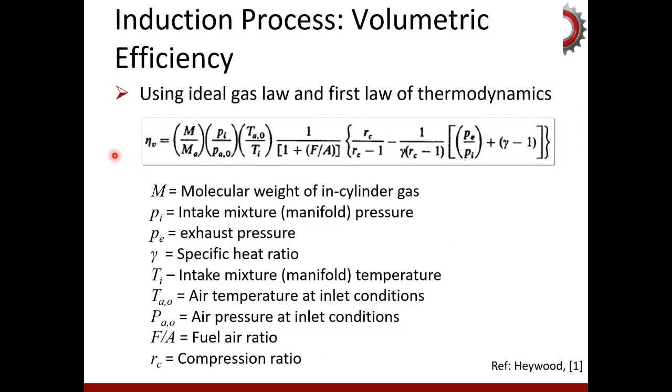So in terms of intake pressure, atmospheric pressure, compression ratio, exhaust pressure, and so forth, all these parameters have a certain effect on the volumetric efficiency. And when it comes to designing the intake system, it is very much important for us to make sure that the volumetric efficiency will be maximized.